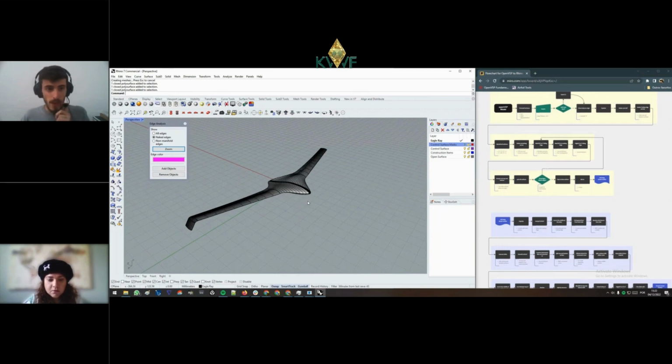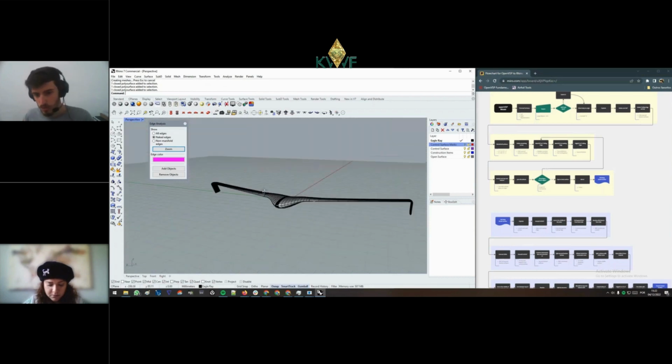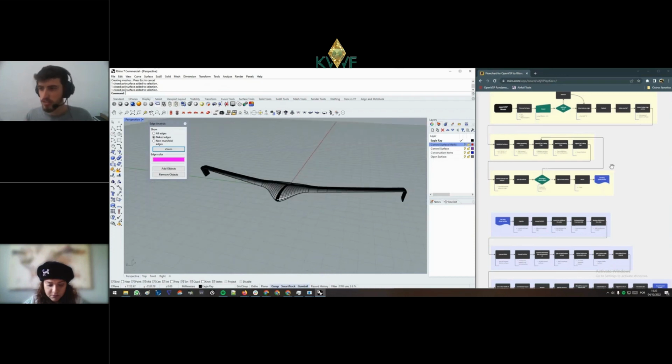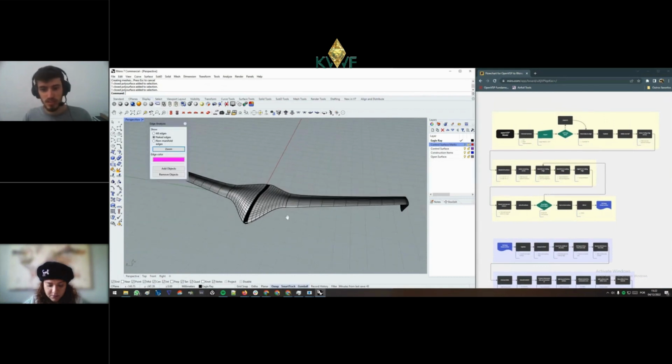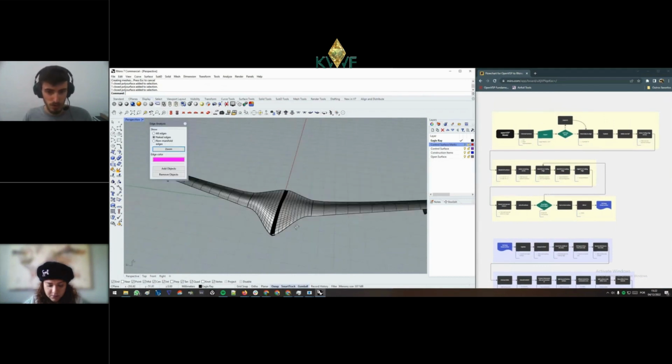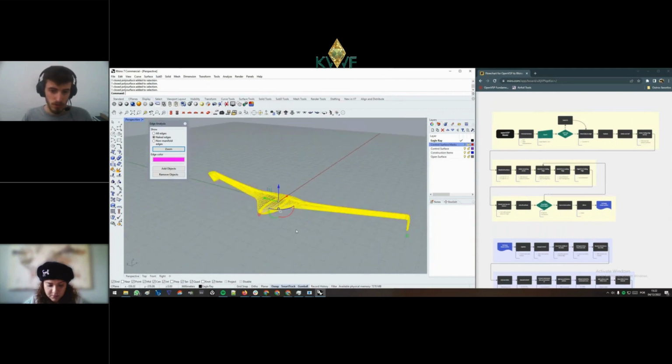Okay, perfect. So this was the step that I think took us longer, going from the exported body from OpenVSP to the closed surface. It took us a while to dial in which were the commands to use and what were the configurations. But with this kind of process, it worked fine. I tried it a couple of times with a couple of different configurations and it all worked. A couple of different models from OpenVSP.